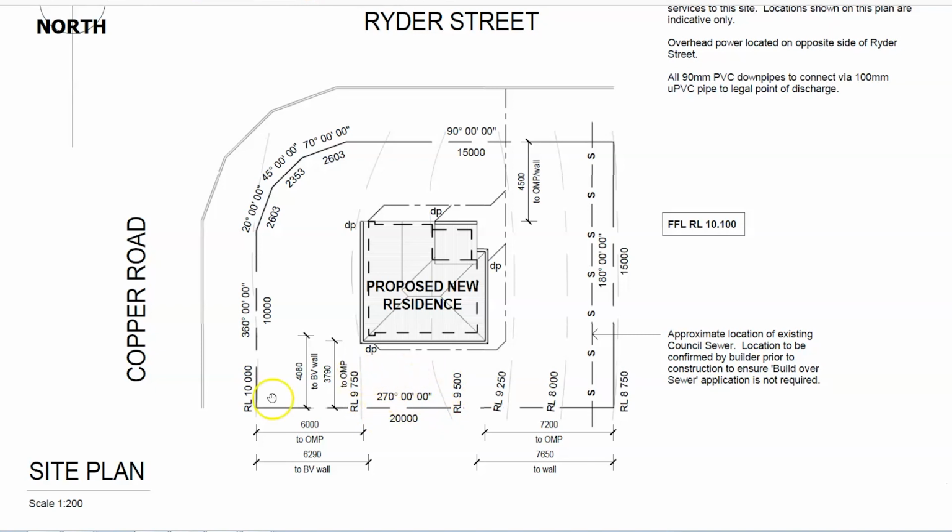And these are marked in to identify the exact compass directions that each of these boundaries follow. And you always go clockwise around the property, so you can see heading directly east is a 90-degree direction, directly south 180, directly west is 270, and heading directly north is 360 degrees. You may occasionally come across a set of plans that calls that 0. It's the same thing. 0 degrees is north, and there's 360 degrees in the whole circle, so 360 is the same.